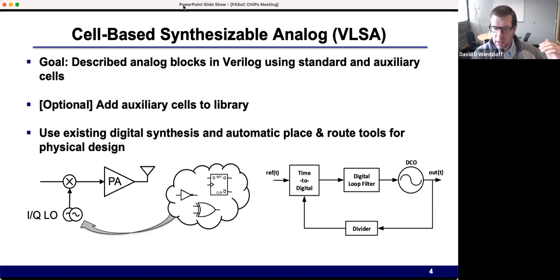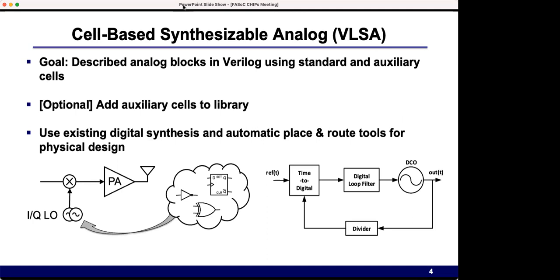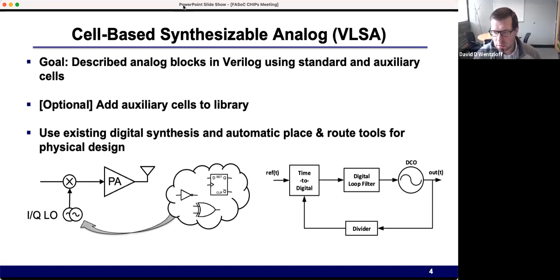No, okay. Actually, you're talking about higher level user specs. When I say behavioral Verilog, I mean you can type the function, you know, y equals a star b, and that will get implemented into a multiplier. So you can use your standard, more abstracted Verilog to code up, let's say, calibration circuits, or built-in test, for example, or design for test.